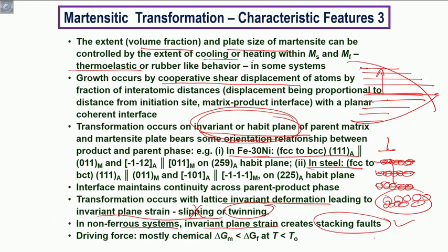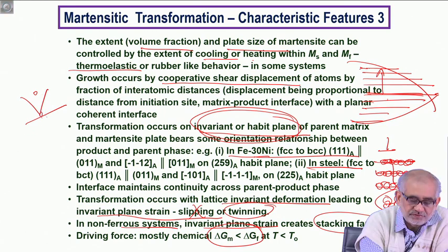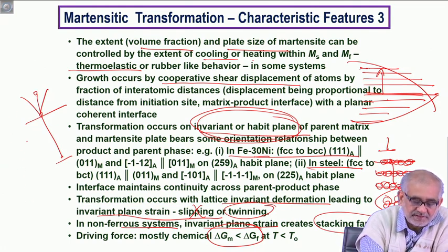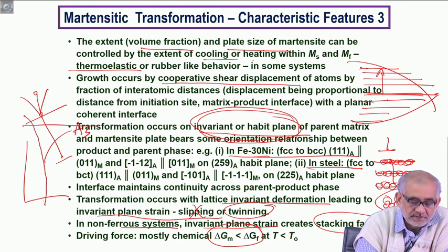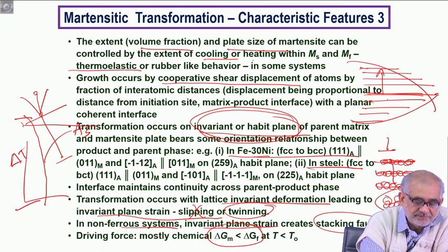strength. The most important part that we must remember is that the entire driving force for martensitic transformation is primarily of chemical nature, which essentially means that if this is the austenite we are talking about, and if this is the eutectoid point, when we quench all the way to very low temperature, so this is in terms of the phase diagram, and in terms of the kinetic diagram, if this is the austenite start, and if we are quenching from way above austenite start to way below, then this large delta T is proportional to a very large supersaturation, and this is exactly the driving force